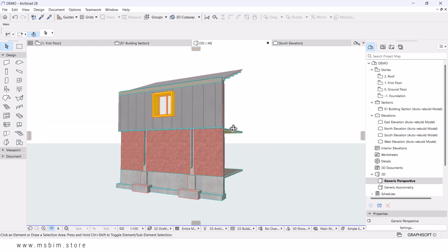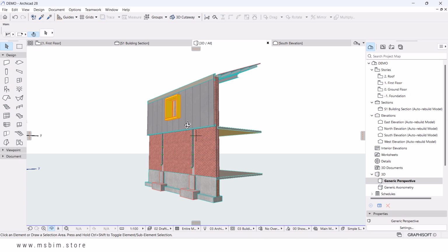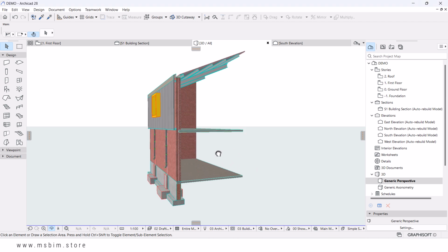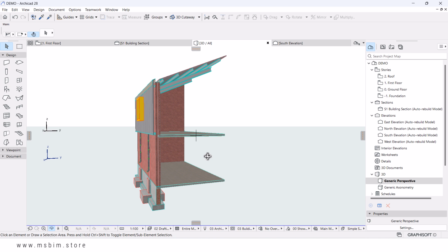It's the right time to generate the drawings. Alright, once you've assembled a great model, it should be pretty easy to generate drawings, right? But before you can think of generating the drawings, you need to put into consideration the pen sets, your graphical theme. So you have to come up with a concept on how you want to visualize your elements. In this case, I'm going to set up my pen sets that all these elements are going to be represented.